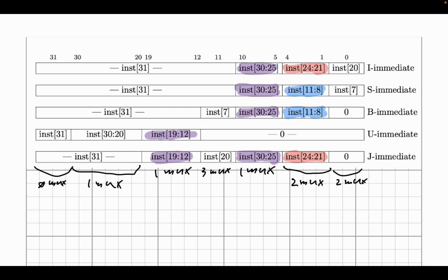So here we are back at the immediate instruction formats, and we can see the sign extension that's happening here, right? Because this single bit, the 31st bit of the instruction, is going everywhere from bit 11 all the way up to 31. So that means this is like 20 bits that we have to sign extend it. So n equals 20. So that means that we're losing, because of fan out, a factor of like 20 in performance.